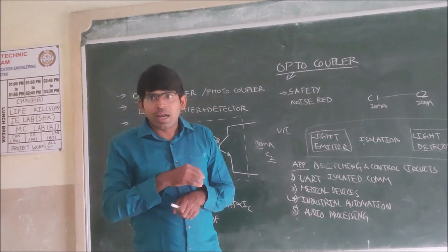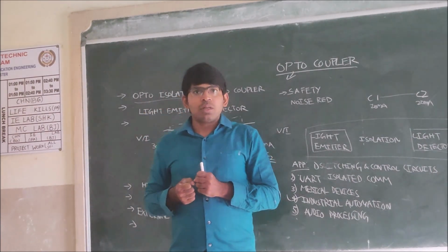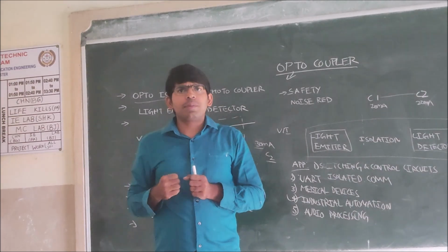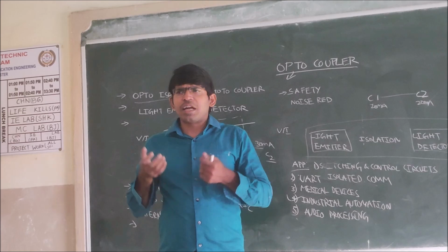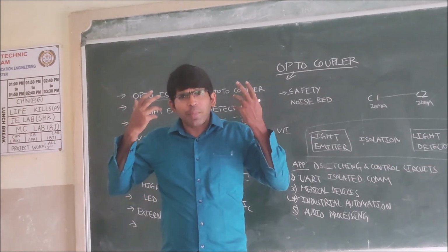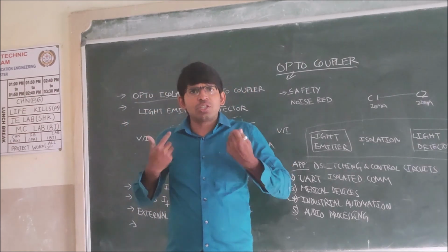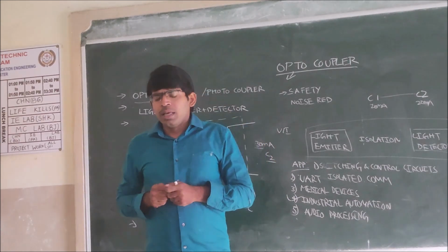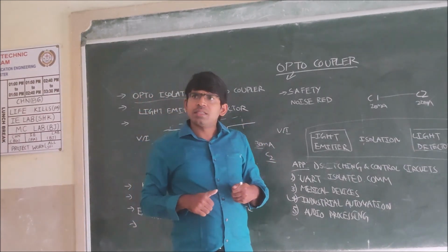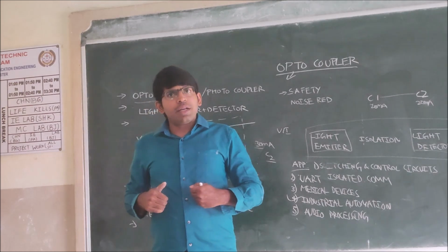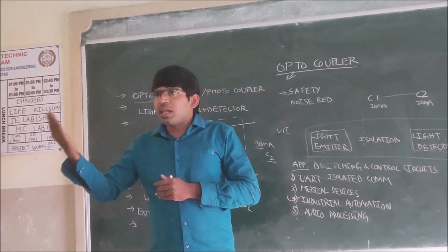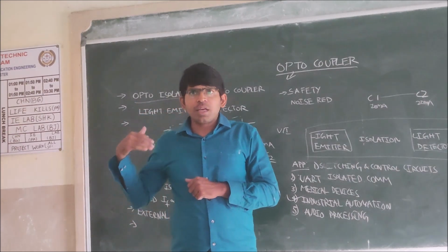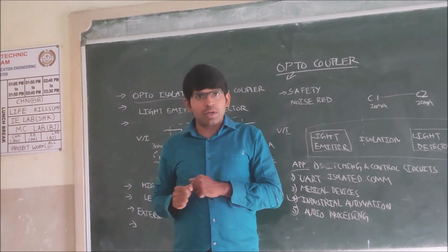Sometimes we connect electronic equipment to patients in order to check their heartbeat in the ECG, and to monitor the blood pressure continuously. They might have some electronic devices in the operation room or the ICU. These electronic devices connected to the patient should be isolated from the outside electronic devices, because those might have a huge amount of voltage.